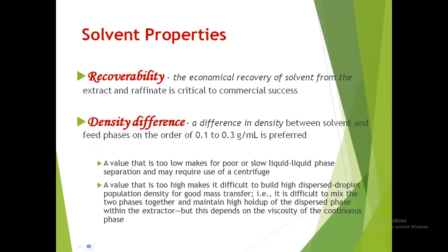Now, recoverability. I have mentioned this several times already. It is very economical, and it is suggested that your solvent can be further reused. The economical recovery of your solvent from the extract and raffinate is critical for commercial success. It's not just a one-shot deal. As much as possible, we want our solvent to be recycled and reused.